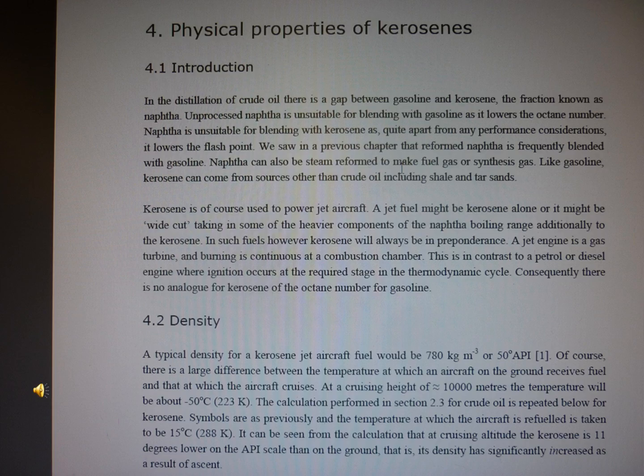Talking about solid deposition, the temperature at which wax appears is an important factor in jet fuel specification. At the cloud point the wax appears. In the specification for jet fuel, take note that a value of minus 47 degrees centigrade applies in some countries. The jet fuels commonly used have a cloud point not above minus 50 degrees centigrade.